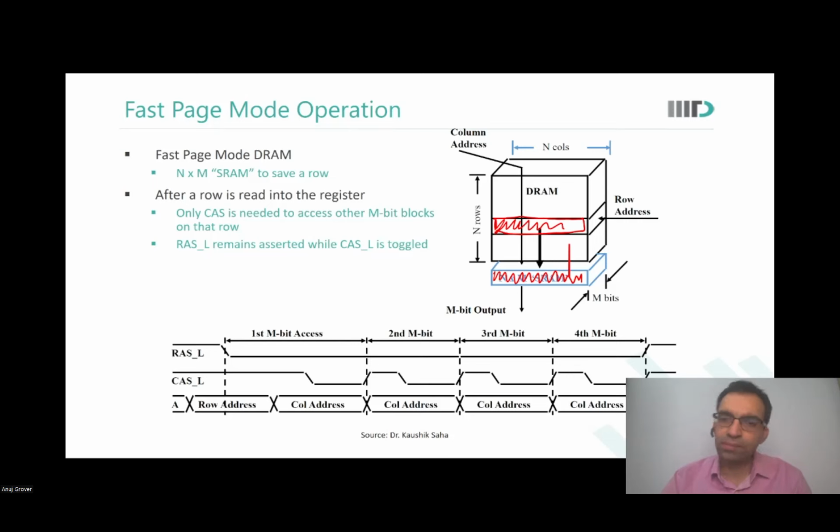Are you with me, sir? Similarly, now there are M pages. So for all the M pages, these N columns would have been read. So in fact, by the time the read operation completes, I have actually accessed M cross N cells of the DRAM.